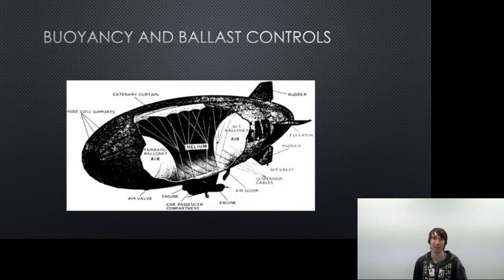This allows air to be transferred into two separate locations within the airship, one in the front and one in the back. By utilising this design, the ballast aspects can also be controlled, as the air can be pumped or removed into either or both sections at any time. I'm currently investigating a method to make the ballast controls an automated system to improve on its effectiveness.